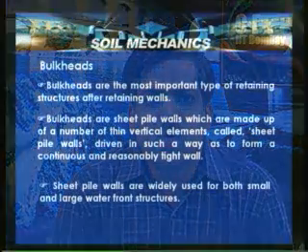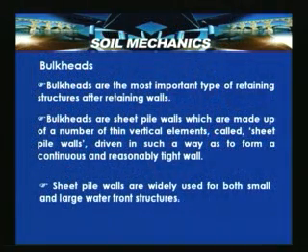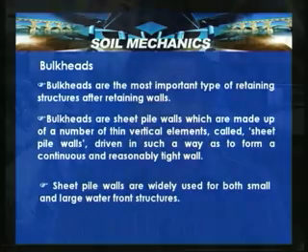But commonly the walls which are going to be designed, like gravity walls, gravity masonry retaining walls or reinforced concrete retaining walls, all require a computation of earth pressure, and based on that the moments are estimated, and then wall stability from the sliding, overturning and eccentricity points of view can be considered and designed. But let us look into what these bulkheads are and how they can be analyzed for arriving at their design, whether they are stable or not, and how they will deflect if they are anchored, with anchor or without anchor.